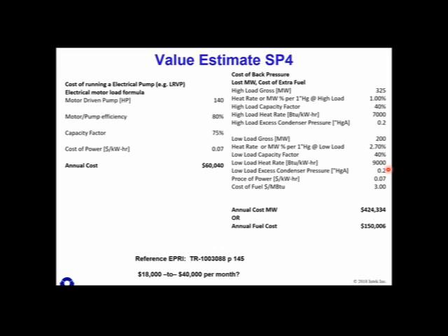And so at this point, this is actually this year, not 2015, but 2018. They had some high back pressure due to air leakage. The excess back pressure due to that air leakage was quantified to be about 0.2 of an inch.